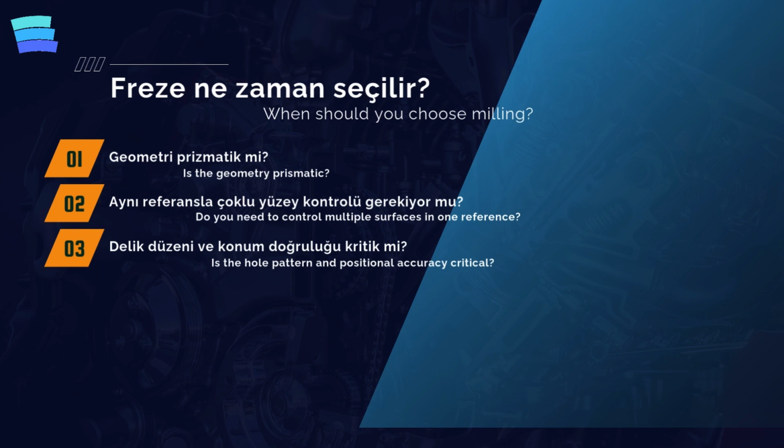If the design is dominated by flat faces, pockets, channels, shoulders, and profiles, milling is usually the shortest path. 2. Do you need to control multiple surfaces in one reference? Machining multiple faces or features in a single setup carries parallelism, perpendicularity, and positional relationships more reliably. The real gain is often not speed, but fewer clampings and fewer in-process checks.